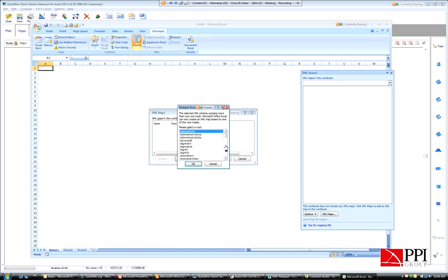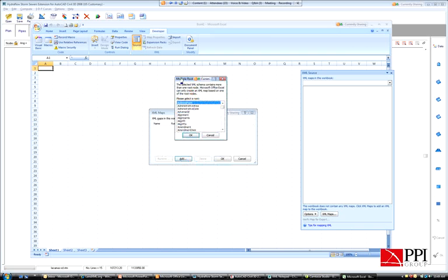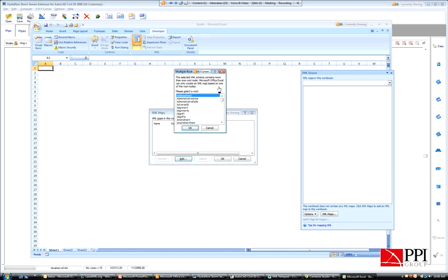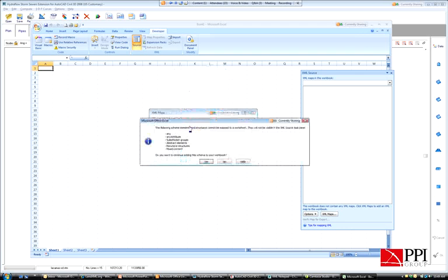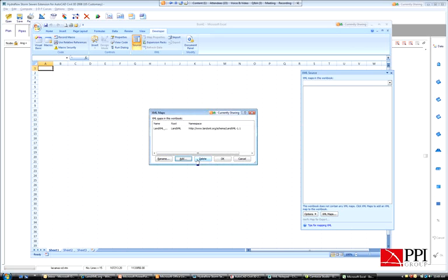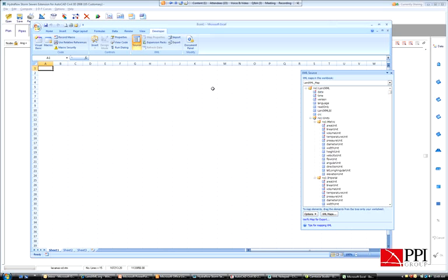I'm going to say open there, and there's multiple schemas available within that XSD, and what you're going to want is the LandXML schema. So that's going to bring in everything that any of these programs read. So right here, halfway down, say OK. Yes. Say OK. And quickly that opens up this huge window, everything in the world that you can imagine.